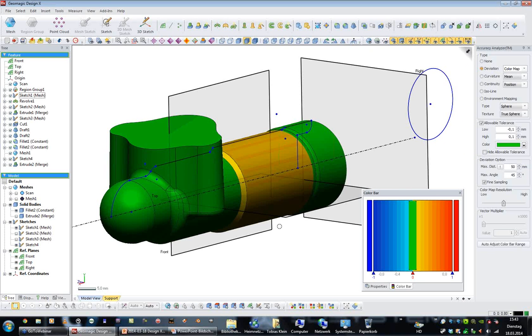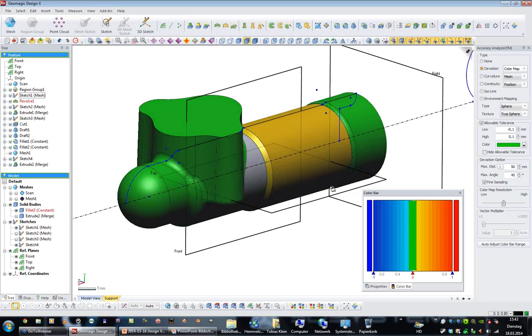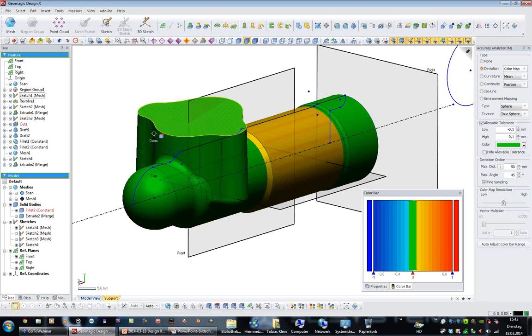This package is more targeting industrial, or let's say prismatic design. So if we want to have very industrial shaped features, then we are using this package. And the other benefit is if we have a CAD package which is already using a parametric history tree, then we have this parametric history tree here which we can transfer one-to-one to the CAD package. So this is the best software if you are already working with a CAD package and you just want to transfer the part reversed here into the CAD package.